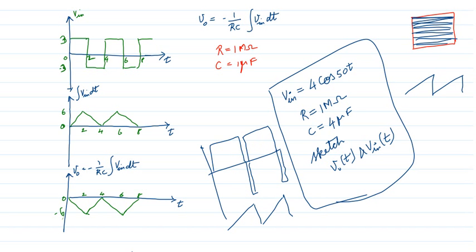Based on the signal requirement, we can convert a square wave to a triangular wave. You just have to control the width and amplitude of the waveform. Thereby, we will get a sawtooth waveform or a triangle waveform signal of our interest. So for wave shaping applications, the major application is wave shaping, we are using this integrator and differentiator.